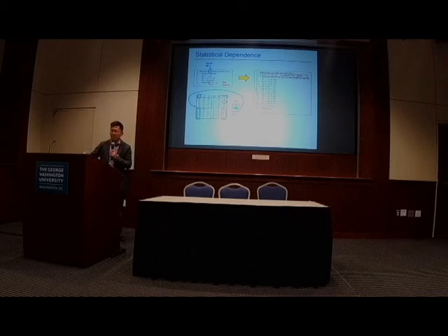And what people end up doing is they use some cheaply generated random bits to scramble the computation. You still have the same 3 inputs, the same 1 output, but in the middle, all the intermediate computation results are scrambled and masked. So if you build a truth table for them, you see 50-50. It's a balanced number of logic 1s.